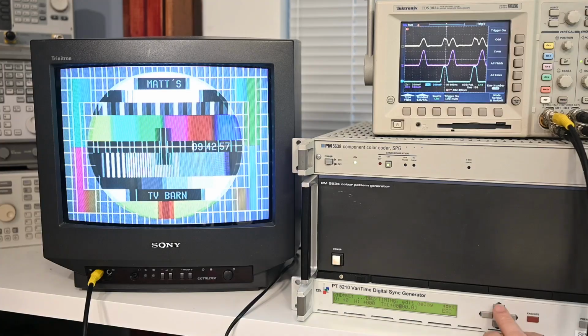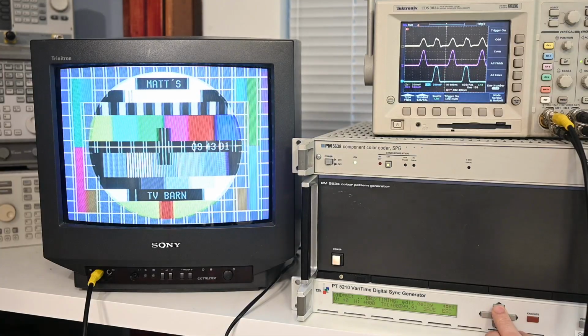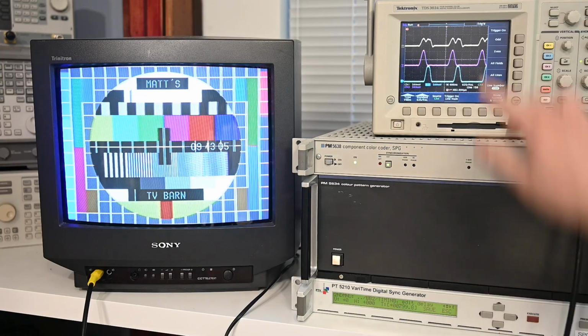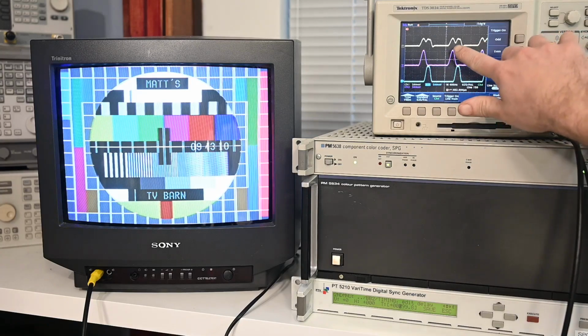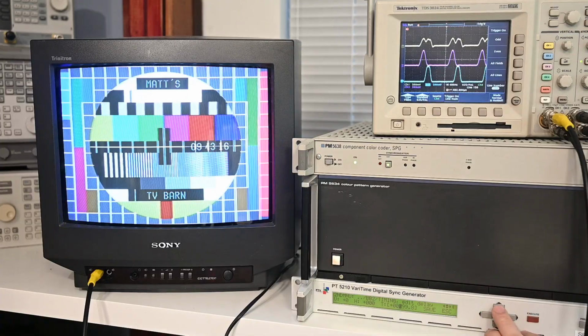So we're just going to start incrementing numbers and see what happens. Now on the oscilloscope here, you can actually see all the three signals of interest. The yellow one is the output of the video mixer, the blue one is the Philips generator, and the purple is the AJA Kona. As you can see, as I increment this, they're starting to line up.